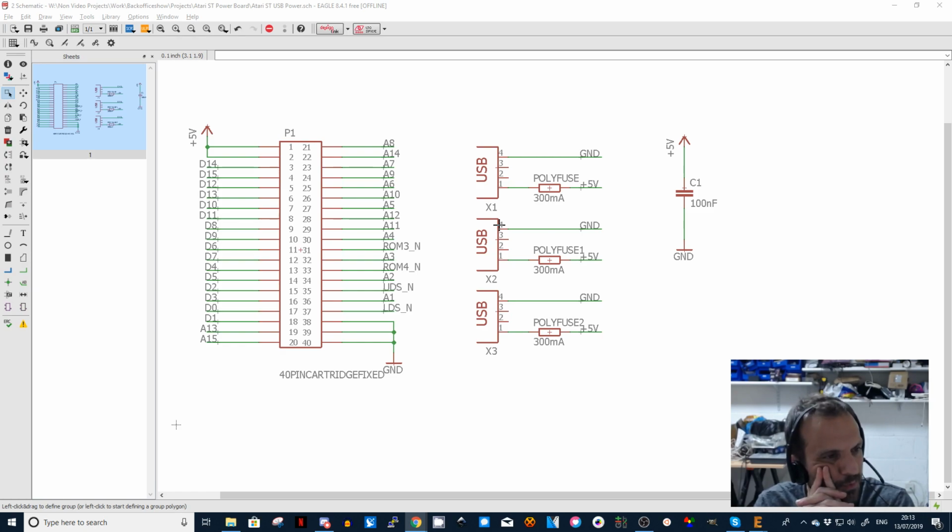Ash, I don't know actually. Why would you need some hefty MOSFETs? I don't think you'd need too much. Just a couple of, like a Darlington would be all right, wouldn't it? There's no back EMF, there's nothing going to be on this. You've got 5-volt input, hefty 5-volt TTL input from the cartridge port. That would be plenty enough to hit that base hard.